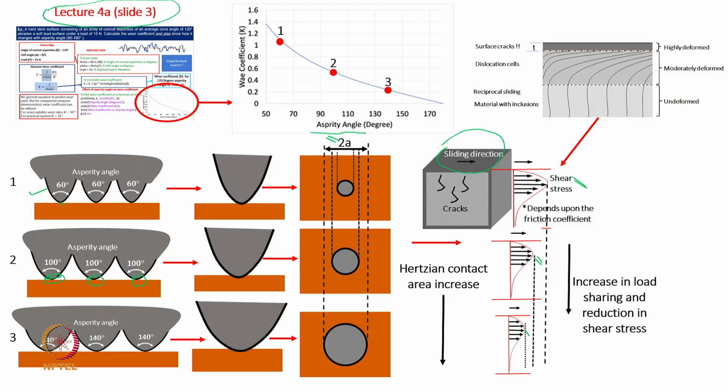In my view, they are interrelated, and for fracture we need to think from the separation of a debris particle from a surface. We do not have to think of complete fracture or complete separation of the material through the thickness. We need to think about the debris that is getting separated, and from where the debris will be getting separated.